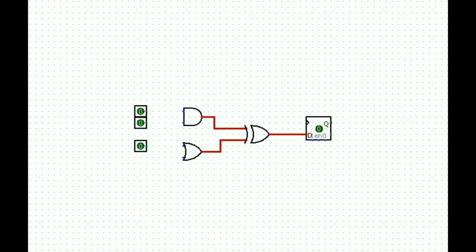It's pretty nifty. Anyway, we're placing a flip-flop, an OR gate, an AND gate, and an XOR gate. We're going to connect them up. We're going to have 4 inputs in this design, and it's going to be registered. So it's going to go through the D flip-flop and 1 output, and the clock also. The clock is an input. So this shows you the basic functionality of the circuit that is going to be coded up in VHDL. It's pretty simple, just 1 register, 3 logic gates, and there's not much more to it than this.